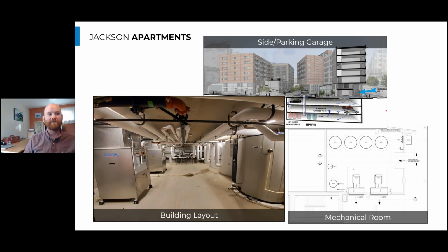When this project was designed, we were specifying and utilizing R134A heat pumps manufactured by Colmac, because that was really one of the large commercially sized heat pump water heaters on the market at this time. The Mitsubishi and other heat pumps that we're going to look at later today weren't yet available. And so these Colmac heat pumps utilize R134A, which is challenged when the ambient air temperature is below 40 degrees.